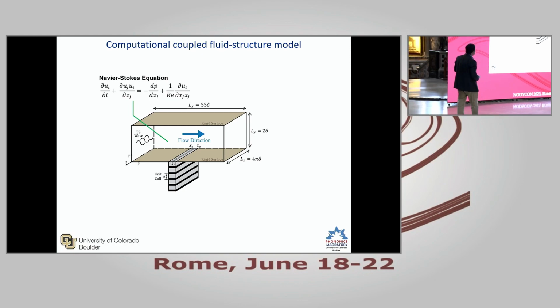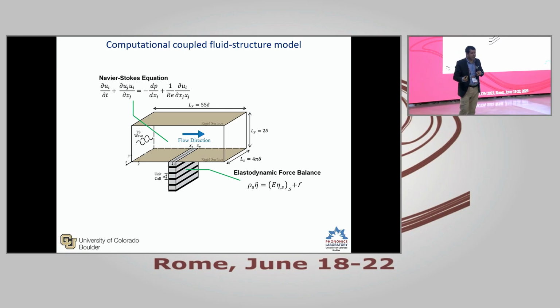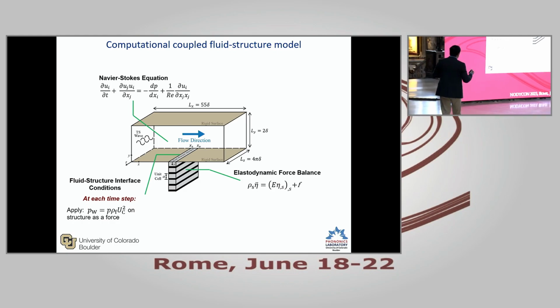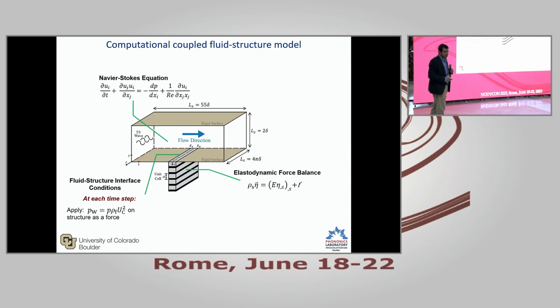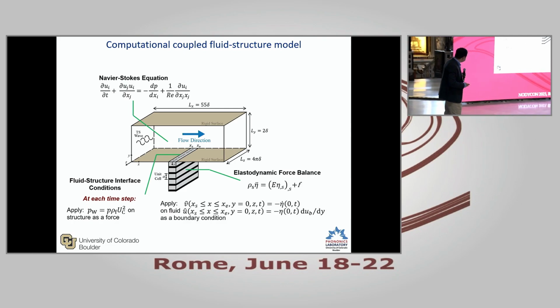So these are the Navier-Stokes equations in the main channel. The solid itself, we'll solve using finite elements, just a standard elastic medium. And then we'll apply flow-structure boundary conditions. We apply what's known as the transpiration boundary conditions. Other boundary conditions can be applied as well.